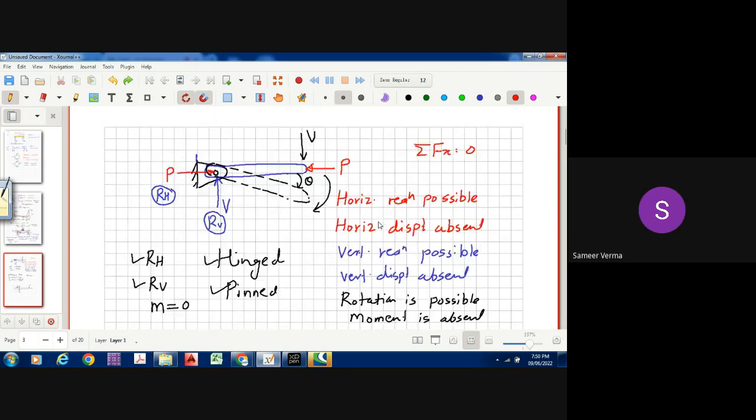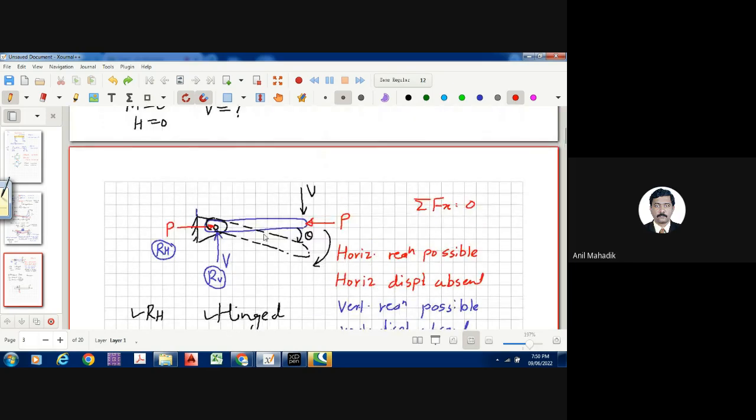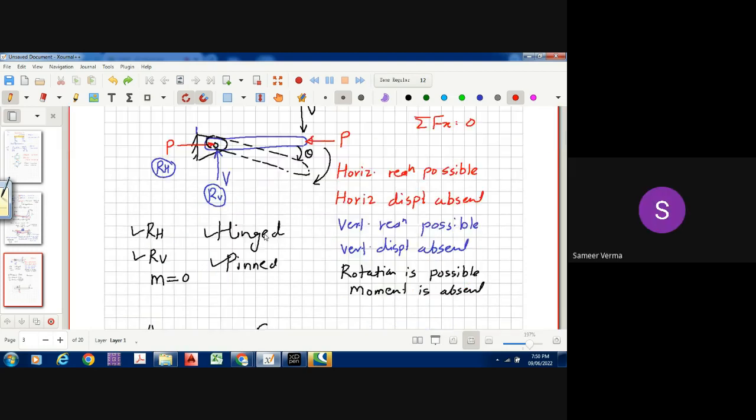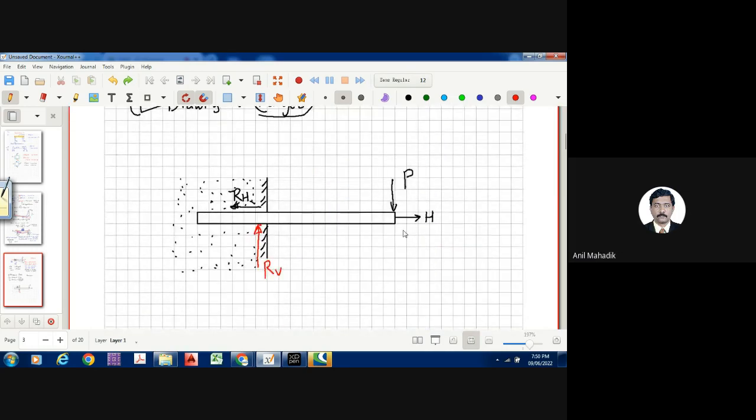जैसे ये, No, rotate sir. ये rotate हो रहा था, ऐसे होगा क्या? No, sir. Will it bend or displace? Bend. या तो bend हो रहा है तो bend फिर होगा. Yeah, bend hoga, but then when it is a bend, there is a rotation, and when there is a rotation, we say moment is zero. तो है क्या इधर फिर moment zero?